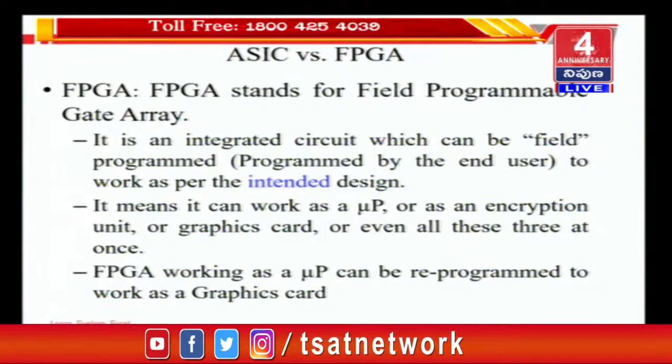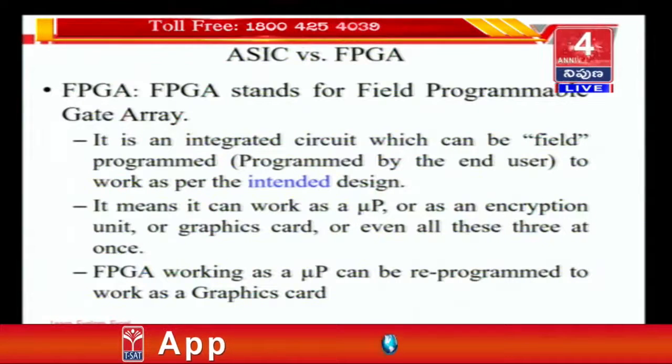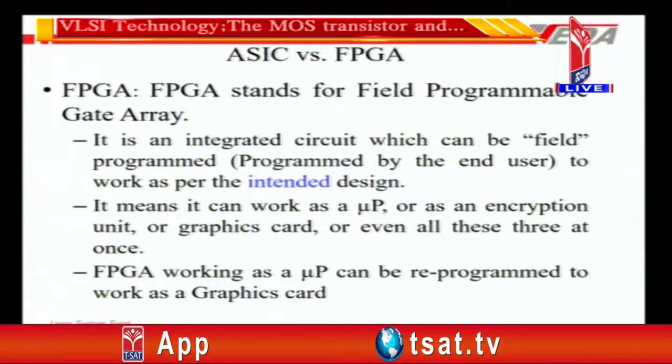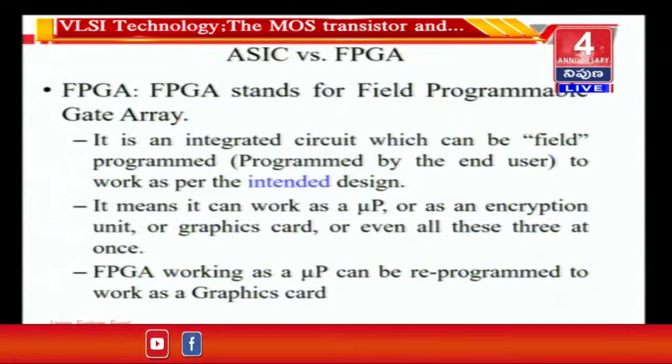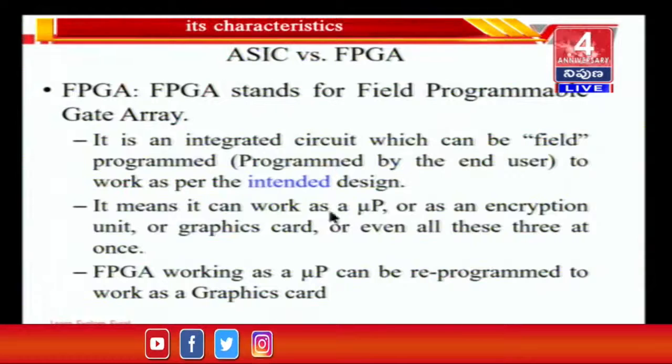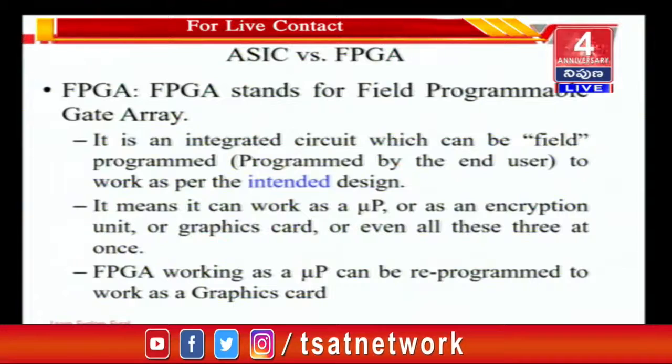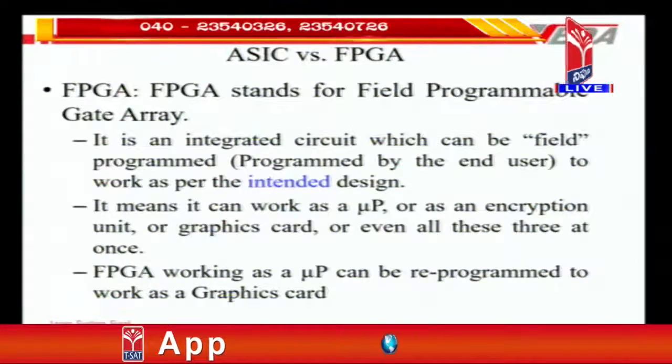No, that's not the meaning of that. Field programmed means to be able to be programmed by the end user, where the actual point of deployment takes place, where the FPGA is actually being used. There it can be programmed to work as per the intended design. So a design is done. In an ASIC, the design gets manufactured, whereas in the FPGA, it doesn't get manufactured. It just gets programmed into the FPGA. You have to put that design into the FPGA, and that FPGA will work as per the intended design.